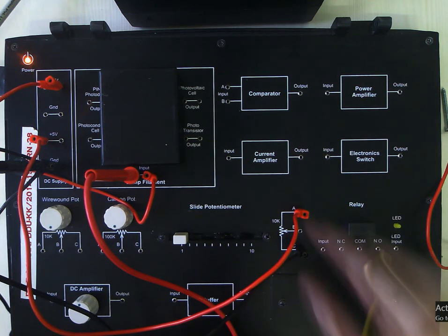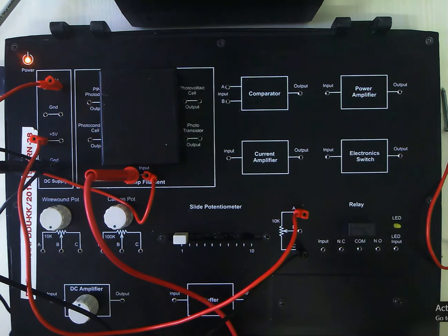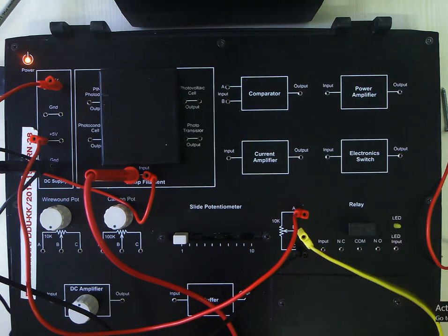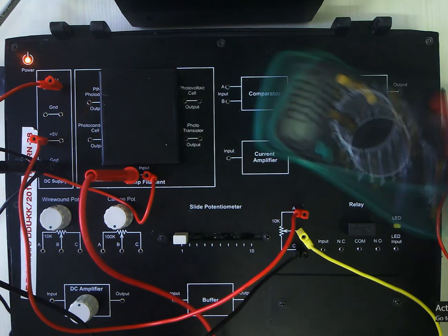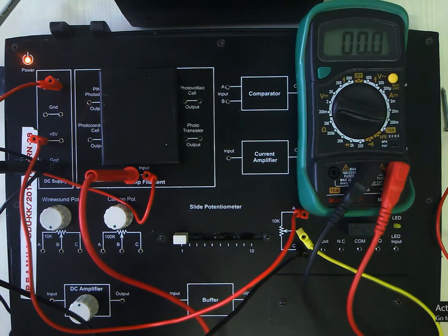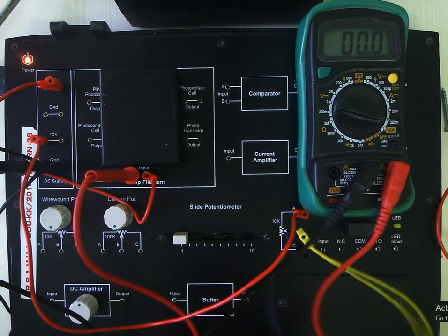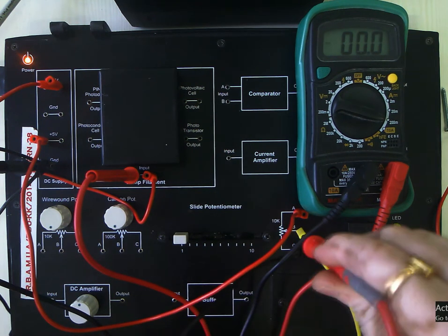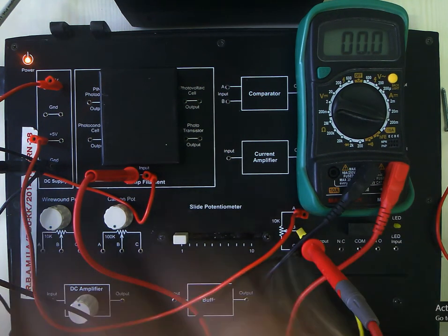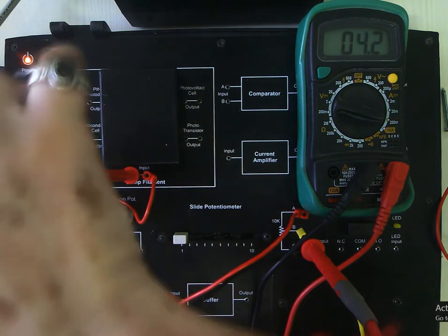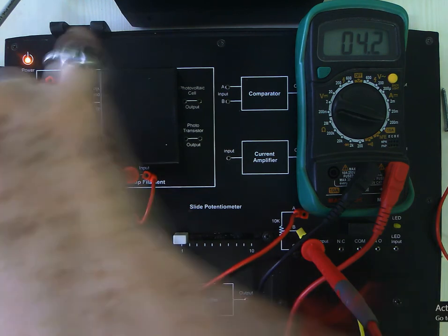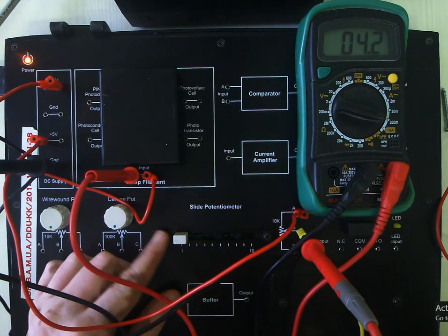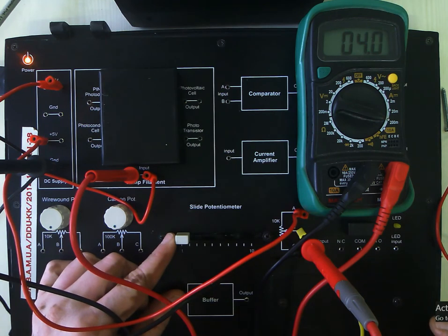Now I will be using this variable terminal. Let us check whether we get a variable voltage here. You see, this is simply a voltage, it does not have the power to drive any load. That you have to be very careful about. Many times it happens that we try to drive a load; if the load has very little power necessity, then it may be driven. So don't try to drive a load while using a potentiometer.